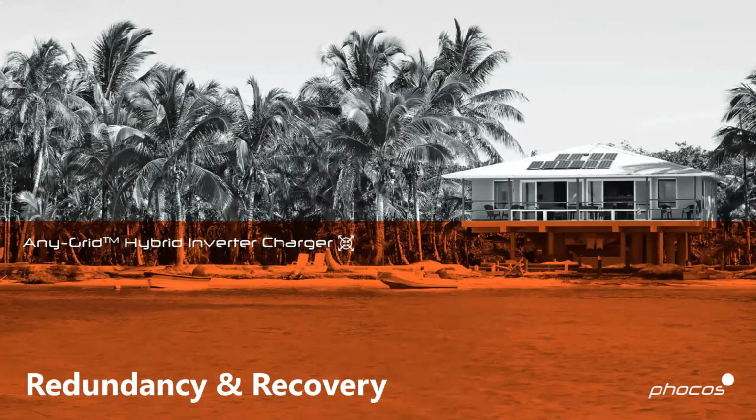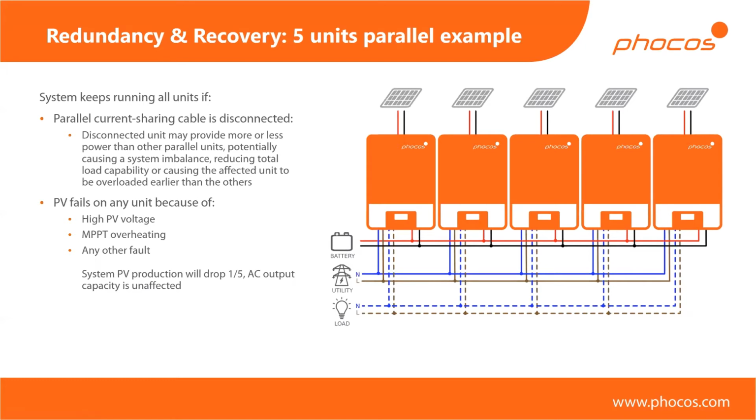Now, redundancy and recovery. This is something we've been asked about by customers, and it's a section we've added compared to the previous webinar from the summer of this year. The system keeps running if any of these current sharing cables are disconnected. There's a reason for them to be there, of course. It makes sure that every unit is providing the same amount of power, so there's no imbalance, but your system won't shut down if you disconnect these cables. So it's just one fault tolerance.